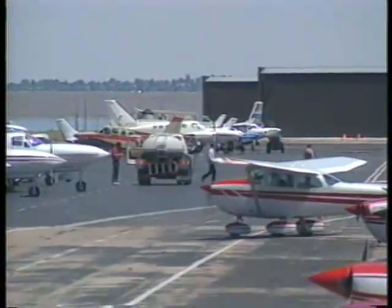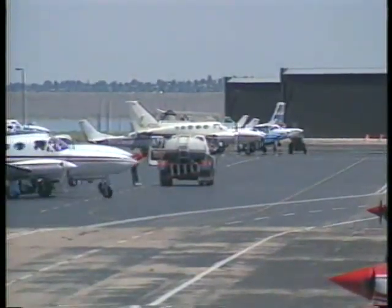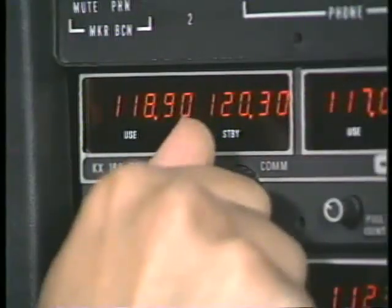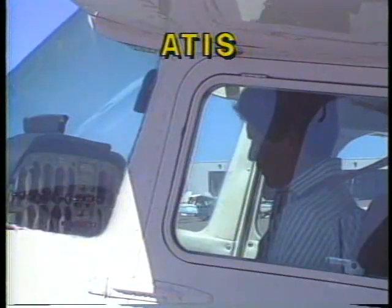At a busy airport, a tremendous frequency congestion would occur if the controller repeated this information to every pilot requesting a taxi clearance. To relieve this, many large airports have a specific frequency for recorded airport information, known as Automatic Terminal Information Service, or ATIS. Each time the recording is updated, it is given a new phonetic letter for identification.